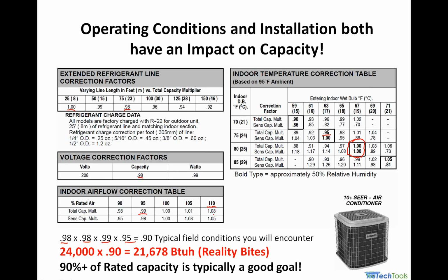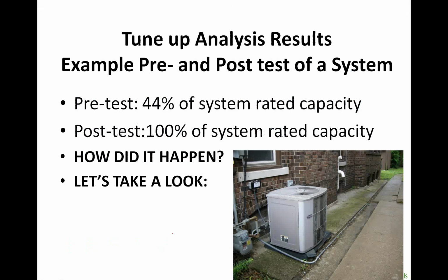Typically we don't want to drop below 400 CFM per ton, because once we do that, even though we get a little bit more humidity removal, we start to lose total capacity of the system. So unless you're engineering it for that, and humidity is your primary concern, and you're engineering it for lower airflow, once the airflow drops, the capacity drops. So very important thing to realize.